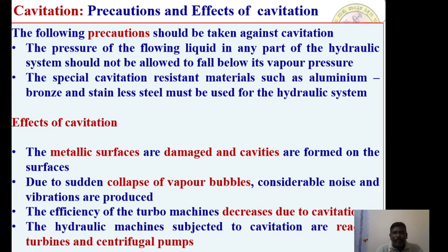When these vapor bubbles are carried to different zones where the pressure keeps varying, and they encounter the highest pressure inside the hydraulic system, a blasting of these vapor bubbles is going to occur. Due to this blasting, the surfaces which come in contact with the bubbles will get pitted and develop cavities.